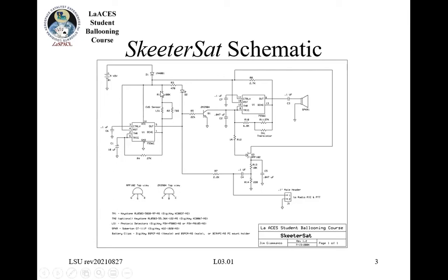The important parts that I'll point out are, normally, there's just a page that the schematic is on. Then you'll see a title block at the bottom with a name on it. There's somebody that made the schematic, and then there's typically a date. You can see this is a pretty old schematic. There also will be a revision history, which is important if somebody makes any changes. And then usually you'll see page 1 of 1, or 1 of 5, or whatever, so at least you know how many schematics are with that design.